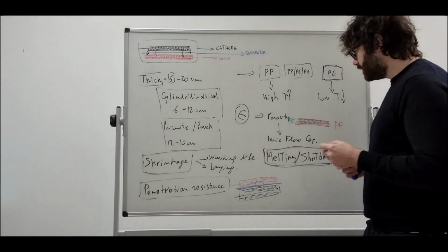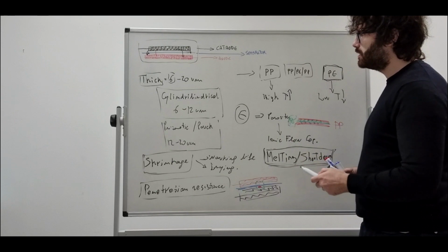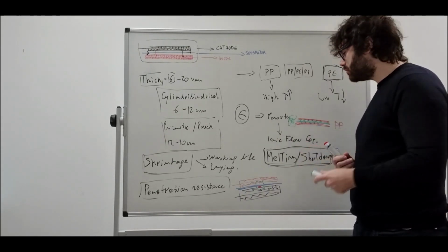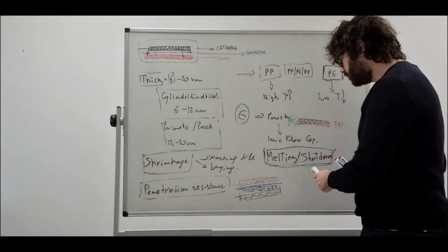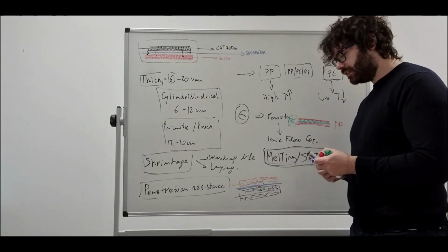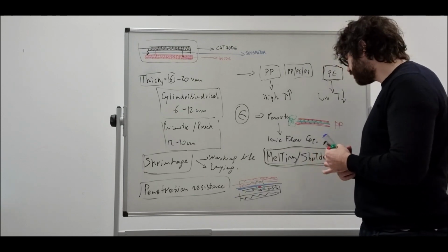Okay, when the micropores are closed, there's no chance for the lithium ions to flow through the separator, and this is called the shutdown effect. Okay, it's a passive safety property of the separator triggered by the temperature.